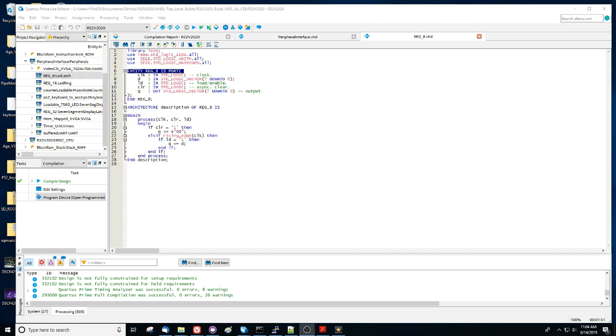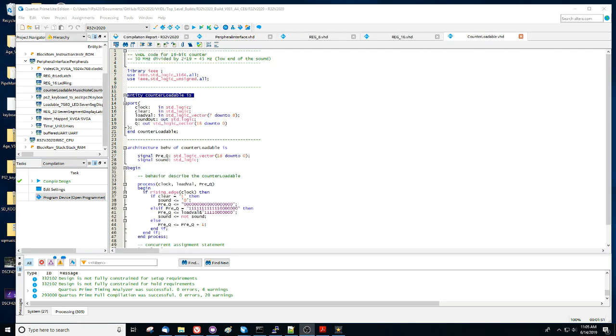The card that we're using has 8 individual LEDs, so there's a latch for those 8 LEDs. The card also has a ring of LEDs with 4 edges with 3 LEDs on each edge, so there's a register for that as well. There's a buzzer control circuit that controls the frequency put to the buzzer. In this case, the card has an actual buzzer, so this doesn't work well on this card. It would just need a voltage applied and it will only create a single tone. But on some of the other cards, the buzzer is more of a little speaker, so varying the frequency will produce different tones and notes.